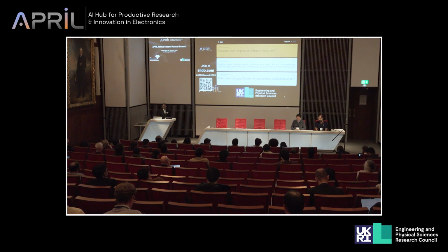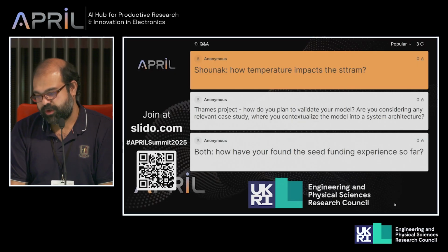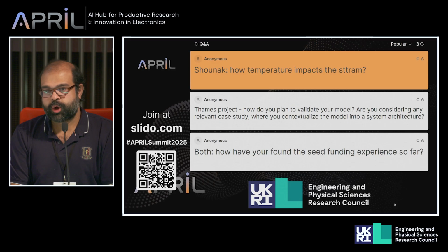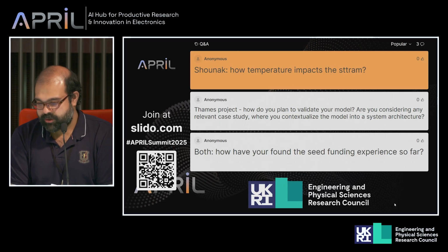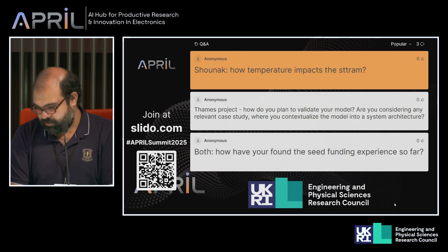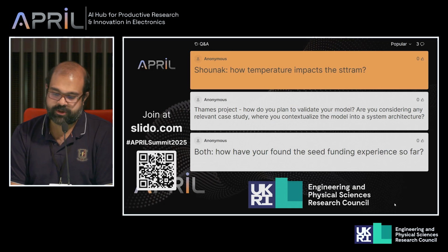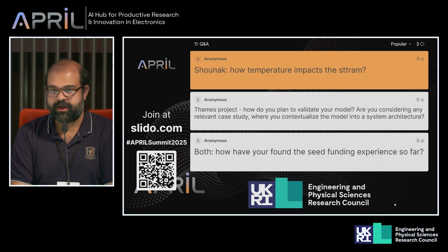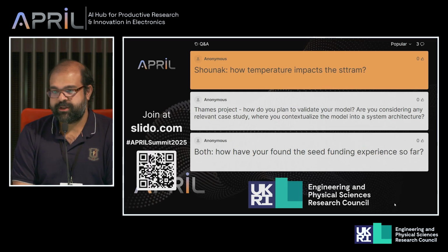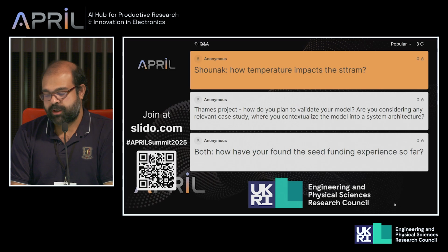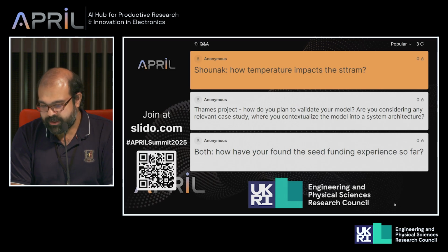Yeah, so at high temperature, basically the circuit delay increases, and that actually impacts the write performance mostly, which we are worrying about for the STT RAM. So write cost in terms of both latency as well as write power and write energy actually increases, and apart from that, the retention time basically drops, because retention time has a strong dependency on thermal stability that further depends on the current temperature of the circuit. So the higher the temperature, the lower the stability, and that actually degrades the write operations.